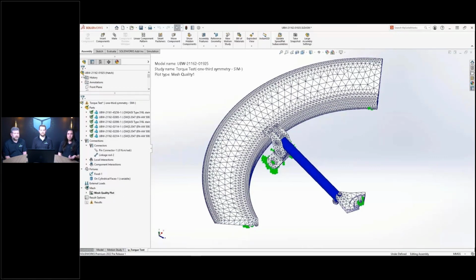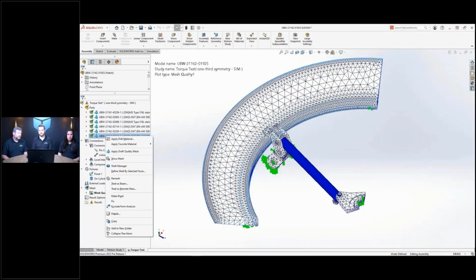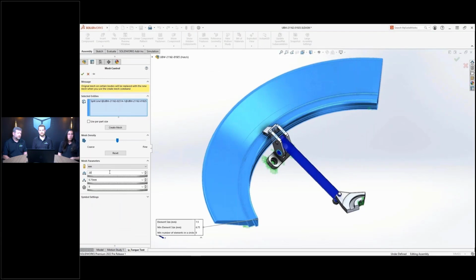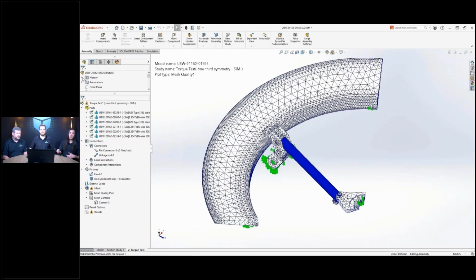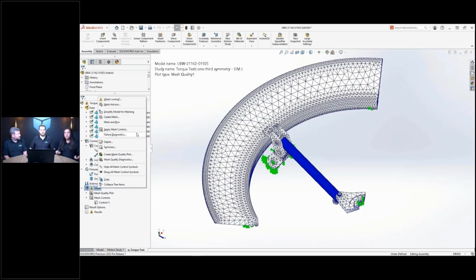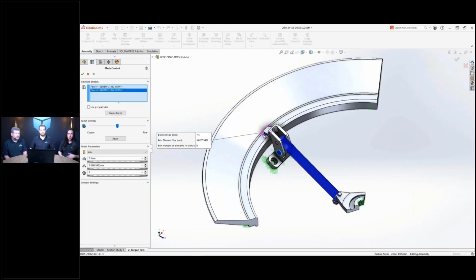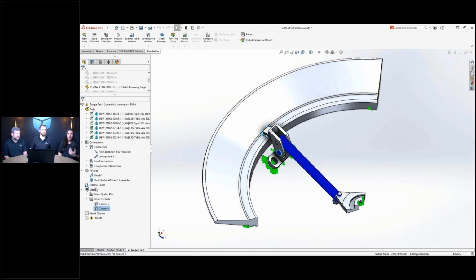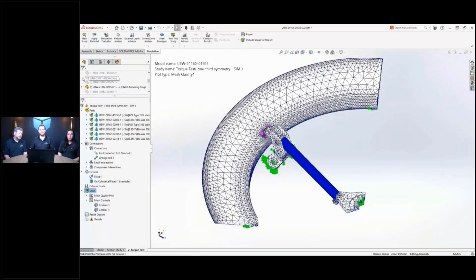The new blended curvature-based mesh gives us that flexibility so that when we mesh the entire part, it's great. We can actually get down to the definition that we want, and we're able to specify some parameters that are beyond what the standard of SOLIDWORKS just automatically calculates. Those are the largest and smallest elements there. We now have added flexibility in those controls to make sure that we have the appropriate mesh density for our small parts so that nothing gets under-calculated. One way you can think about that.